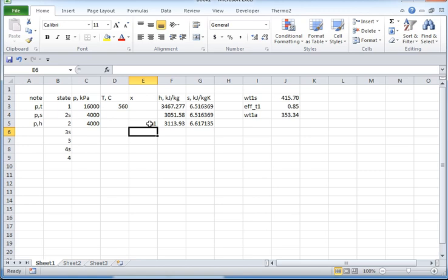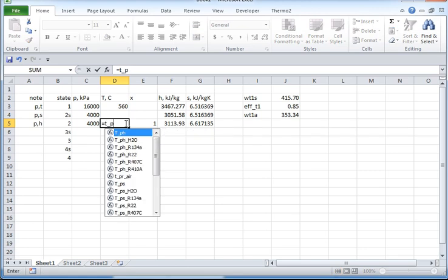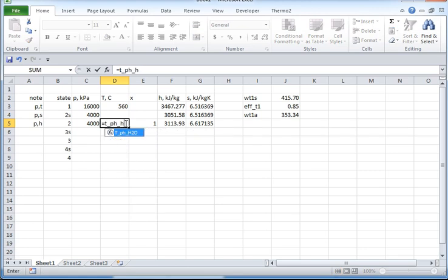That's this software. It's Excel. Either they're going to give you an error or they're going to give you a number back. They choose to give you a number back of 1 when it's superheated. Okay. What about the temperature? Temperature is a function of pressure and enthalpy, H2O. Let's get the pressure. Let's get the enthalpy. And there's the temperature. Now that's too many digits, but let me do this one.